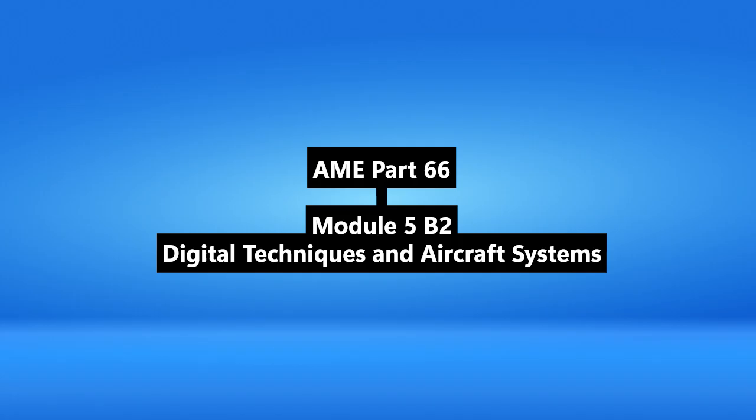Okay, and ARINC 653, how does that fit in? ARINC 653 is about the operating system environment, particularly for integrated modular avionics, IMA. That's where you have multiple software applications, potentially with different criticality levels, different DALs, running on the same processor hardware, sharing resources. Right. ARINC 653 provides strict partitioning rules that guarantee memory space and processing time for each application, completely isolating them. So a glitch in a low criticality application, say level D, absolutely cannot interfere with a critical level A flight control function running on the same chip. It ensures freedom from interference.